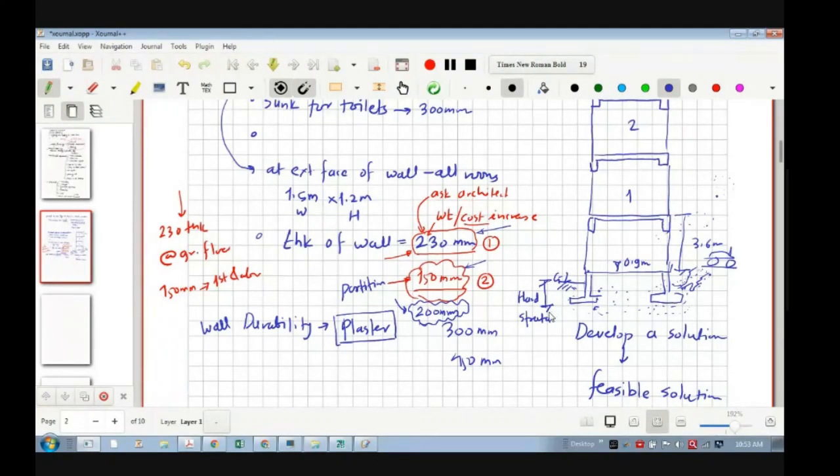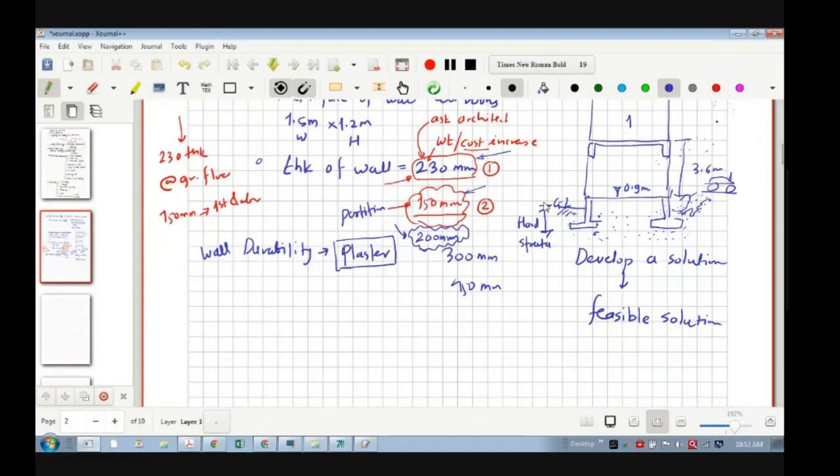सर एक प्रॉपर्टी लाइन का भी प्रॉब्लम आता है जब हमेशा हमें वो एक्सेंट्रिक फुटिंग वगैरह बनाने पड़ जाते हैं, तो वो एक बहुत बड़ा दिक्कत आता है. तो you can ask the architect the question, is there any property line issue, मतलब property line issue or any eccentric footing requirement.